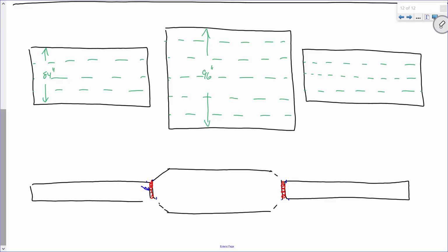But what I would say is if you've got a span arrangement and you can get away with using, let's say, 6 cross frames as opposed to 7, and it's not going to appreciably change your LB, I would do it. Because that's a fewer set of angles and channels that need to be fabricated, fewer set of holes that need to be drilled, fewer set of stuff that needs to be put together in the field. Make sense? Okay.